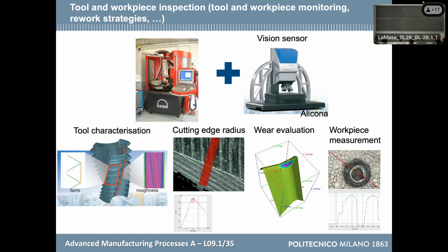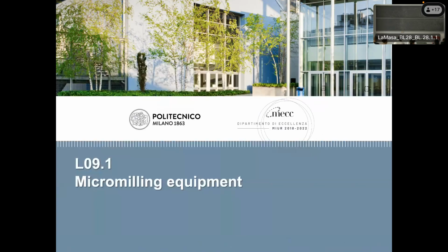The machine we have now is a 5-axis machine itself. So even the measuring machine is a 5-axis, because when you take the part, you can measure all the surfaces you want, and then you can verify the tolerances. You can acquire even the texture, not only the roughness, but I can describe in 3D how the surface is made, which is functional in many cases.